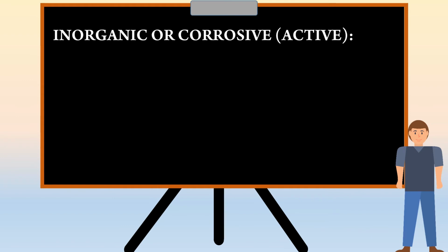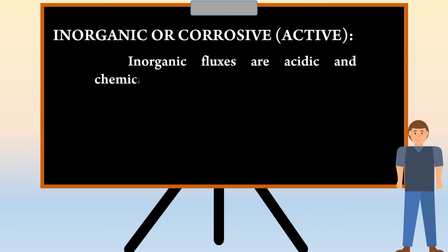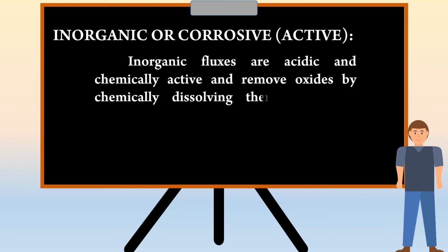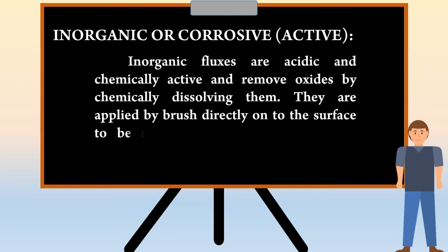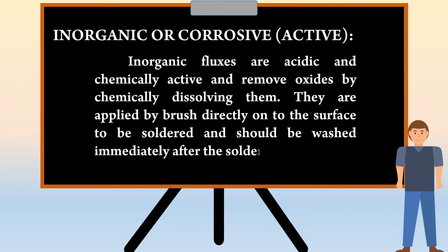Let's see the definition of inorganic fluxes. Inorganic fluxes are acidic and chemically active and remove oxides by chemically dissolving them. They are applied by brush directly onto the surface to be soldered and should be washed immediately after the soldering operation is completed.